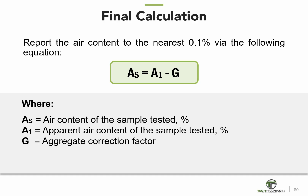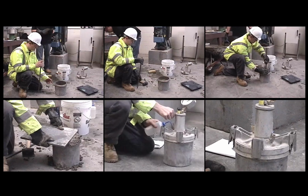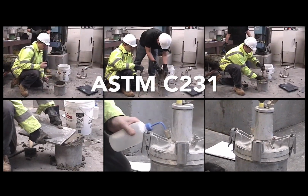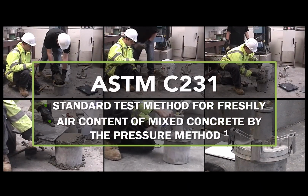So let's assume the A_1, or the reading on the dial gauge, was 6.5%. The G aggregate correction factor is 0.4%. Then the air content of the sample tested in percent, or the A_s, is 6.1%. And this concludes ASTM C231, standard test method for air content of freshly mixed concrete by the pressure method.